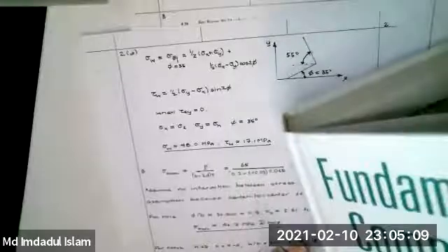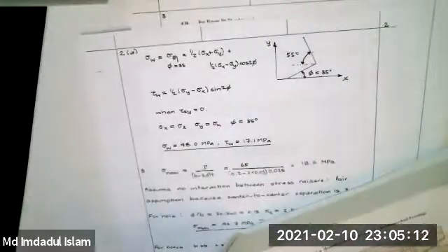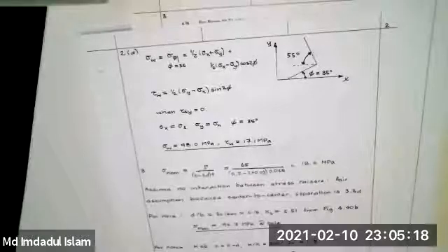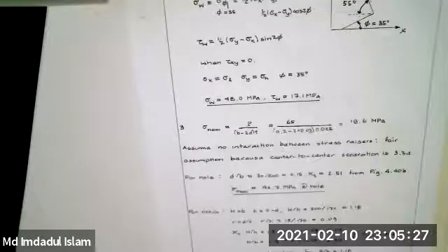We actually had a couple of questions on this problem when MD was going over the homework on Friday, and we wanted to see what was going on. When you're calculating little h for the notches, because you have to calculate h over H, why do you exclude the hole? Why do you calculate it as 170 and not as 170 minus 30?